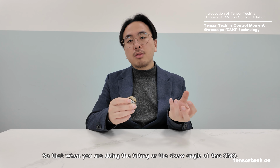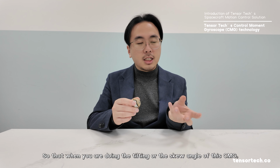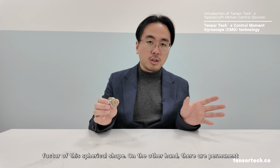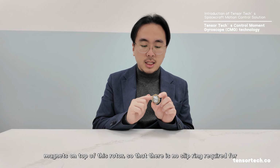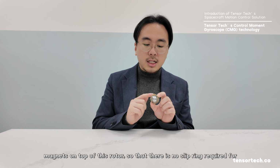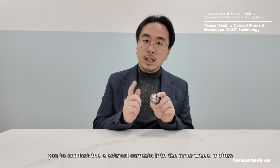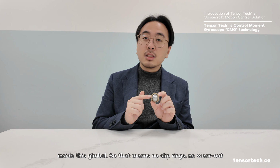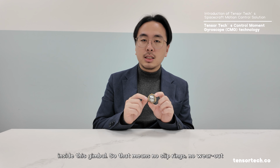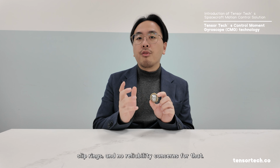So it is able to shrink the size and make the form factor of the CMGs spherical. So when you are tilting or skewing these CMGs, it will not occupy extra space because it comes with a natural spherical form factor. On the other hand, there are permanent magnets on top of this rotor, so no slip ring is required to conduct electrical currents into the inner wheel motors inside the gimbal. That means no wear out on slip rings and no reliability concern.